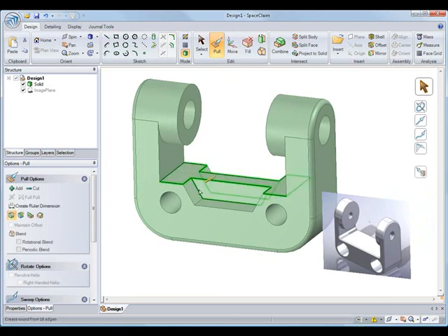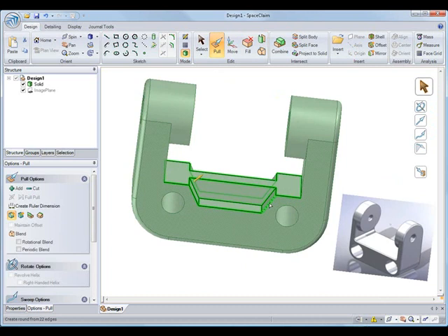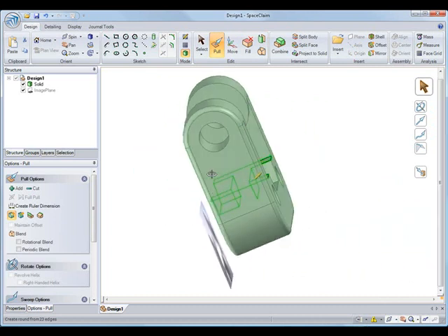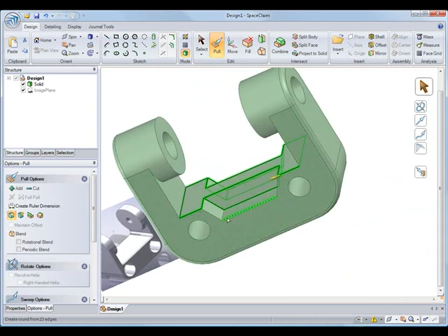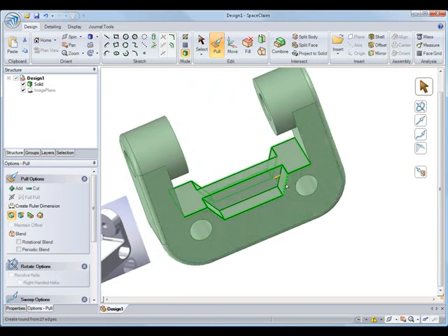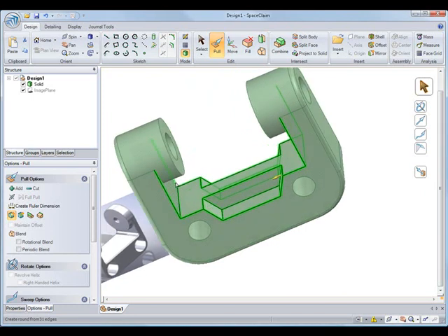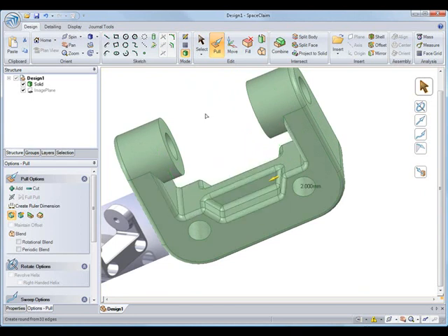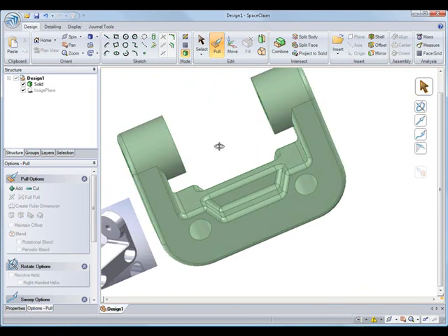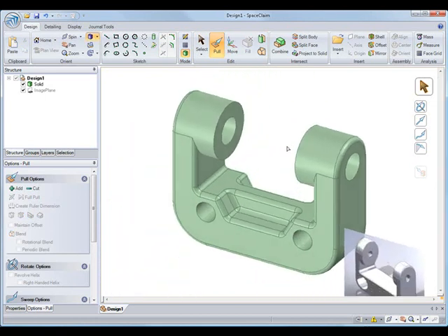So the last thing I need to add by looking at the model is to put some rounds in the inner geometry. So I'll just double click to get most of these round loops, and I'll hold down Control, remember, to select multiple edges. So once I've got all the edges, you can see I only have 4 more. Select on them. I can round them all together at once. And I'll round it maybe 1 or 2 millimeters.